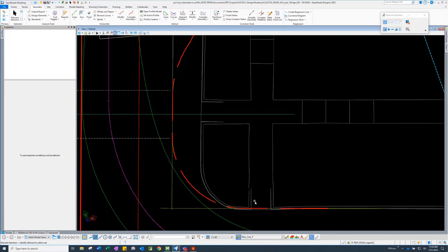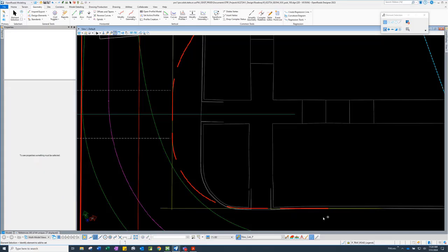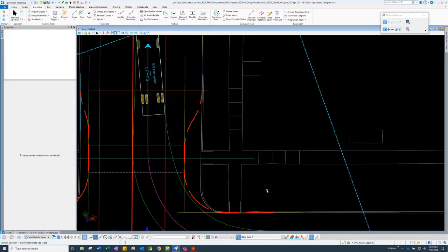So select that last tangent piece again, and you're saying, okay, so we've got a key point snap on the left side there and a near point snap to the control line on the right side. Okay. Correct. And because all of the lines are ruled to basically 2 construction lines and then the end one, if I have to adjust this line, I only have to adjust those 3 construction lines. I don't have to redraw any of the elements in here. I would just have to adjust them, new radiuses, stuff like that, because they're all ruled in 1 unit.